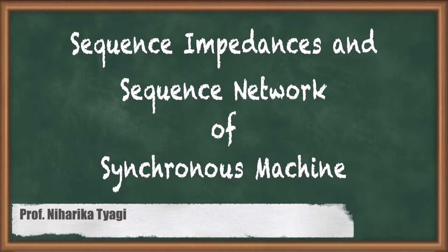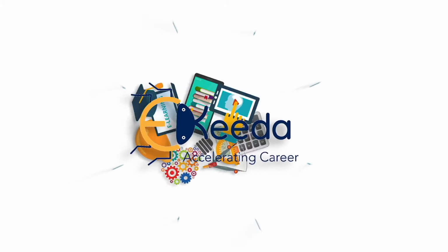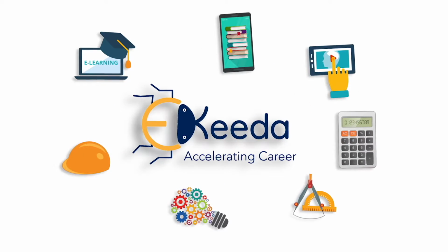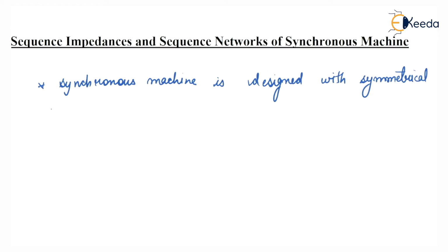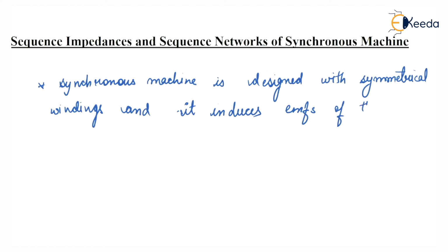The title of the lecture is Sequence Impedances and Sequence Network of Synchronous Machine. So, sequence impedance of synchronous machine. In this case, the synchronous machine is designed with symmetrical windings, and it induces EMFs of the positive sequence only.